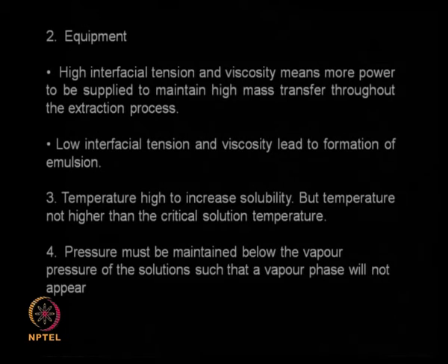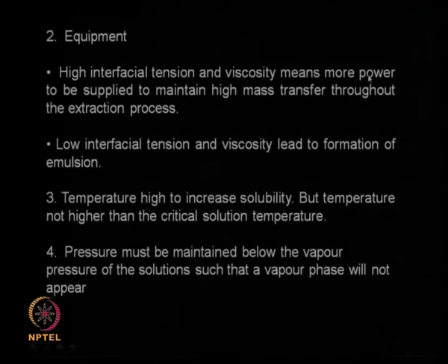Now, let us look at equipment. If the interfacial tension and viscosity are high, obviously I need to put in more power to achieve good mass transfer. If I am mixing two phases and the viscosity is high, I will put them together and I will have an agitator, and the agitator has to revolve faster. So, the power required also goes up.